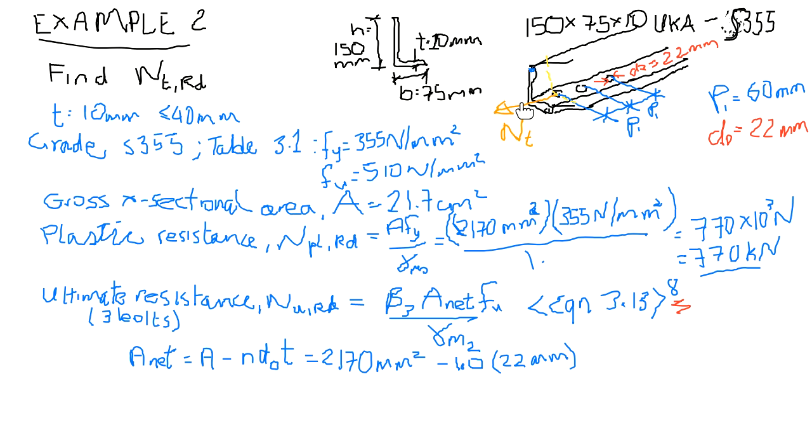I'd have to cut through longitudinally to get the 3 holes. So n is equal to 1. That's a very good question, because that's where loads of people make a mistake. They see 3 holes and they say, okay, n must be equal to 3, but it's through the cross section, and there's only one hole through any one cross section.